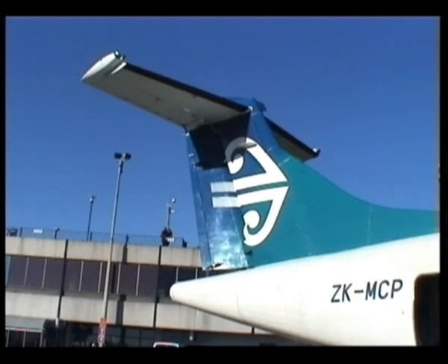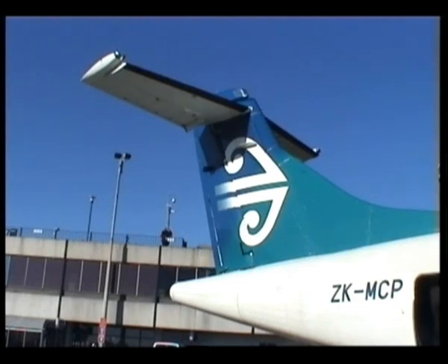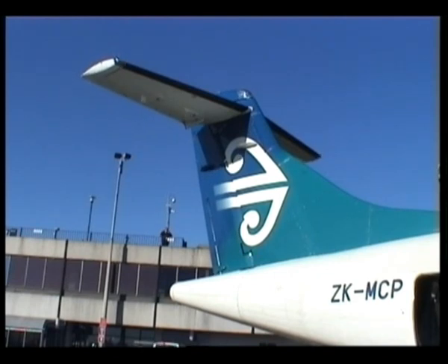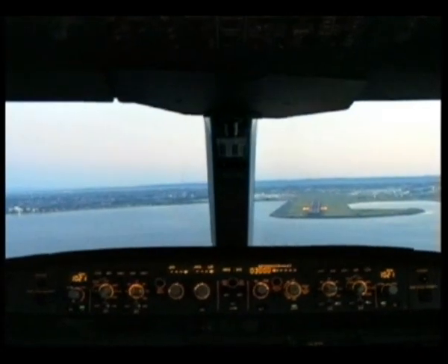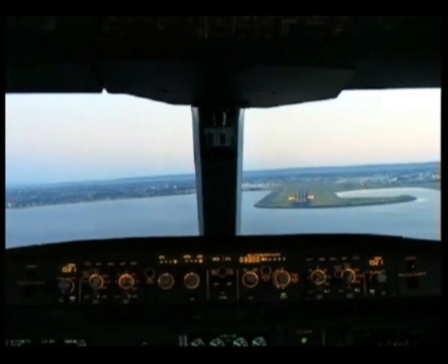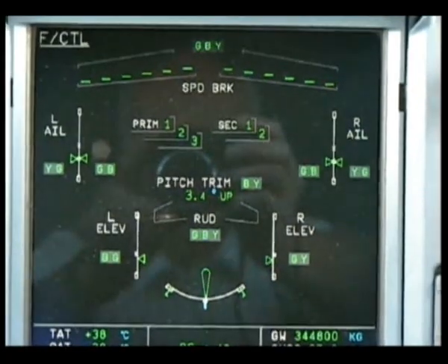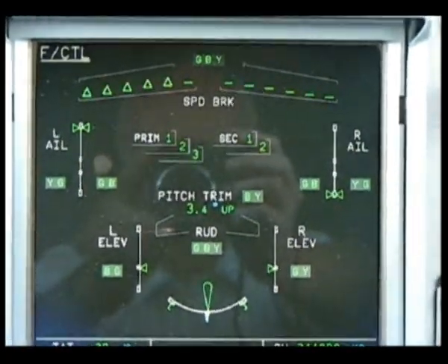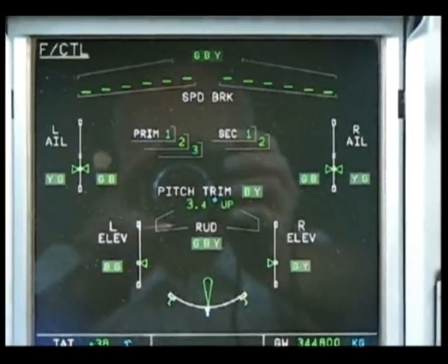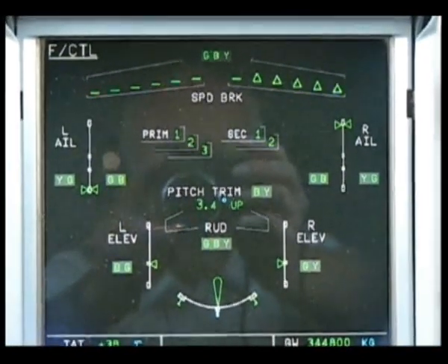The control surface to be fully effective at slow speed may be too effective, difficult, or even too violent in action at high speed. In addition, the controls at high speed may also be oversensitive. These problems have been overcome by the use of power-operated controls, which, when used, means that the pilot cannot feel the controls unless it is artificially introduced.